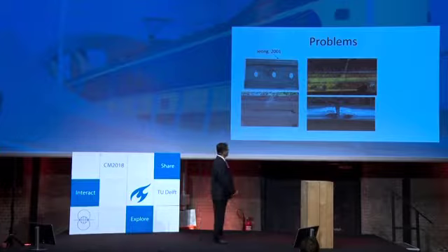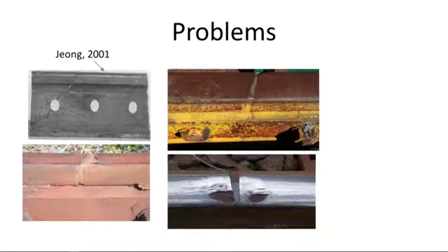Because of the dynamic load, this is the 8 millimeter end post. Because of plastification and plastic flow, the thickness of the end post is gradually reducing. What happens if one rail touches another rail? That means the signaling block fails. That is the controlling problem, the destroying of the electrical signal.